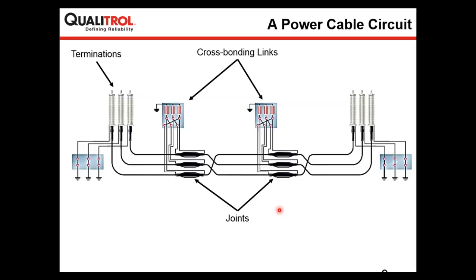But if you have middle groundings or T-joints, then you need to access each cable shield at different joint positions, so that you will be able to zone partial discharges in different sections of the power cable. That is the maximum you can do if you have middle grounding or complex T-joint networks, which normally happens in the distribution network.